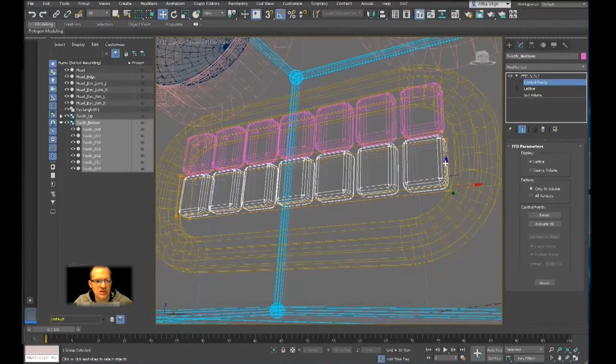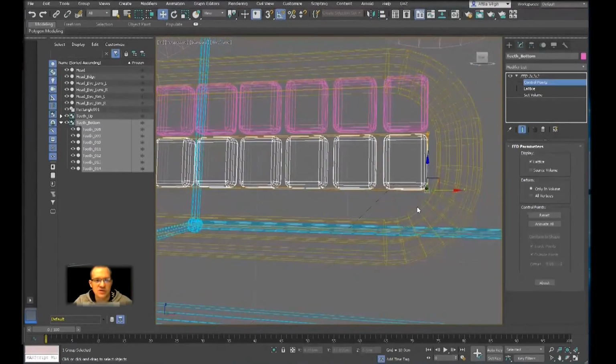If I'm selecting only one side, don't forget, we are using Windows selection. Why? Because simply pointing and clicking can only select a single point. You can't select 2 points in a row. And because we are in 3D, there is a chance that when you think you have 1 point, it is actually 2, because these are overlapping. When you're just pointing and clicking, you think you can select both points because they're overlapping, but sorry, point and click only selects 1. So you have to drag the rectangle to select both.